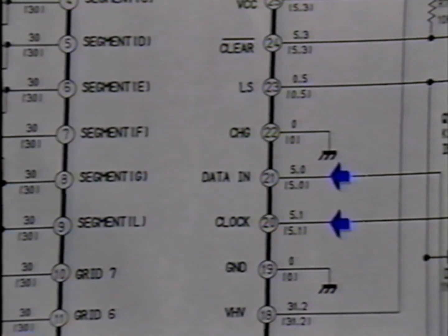The other data transfer control line is the strobe, also called the LS or latch strobe on the Digitron drive. The strobe signal is produced by the system control microprocessor and indicates when the Digitron drive should consider the bits sent to be a command word. This line should pulse as data is sent. When observing serial data communications lines, it is important to be sure that data is being sent. That is, the product may have to be placed in the play mode to observe the transfer of data.